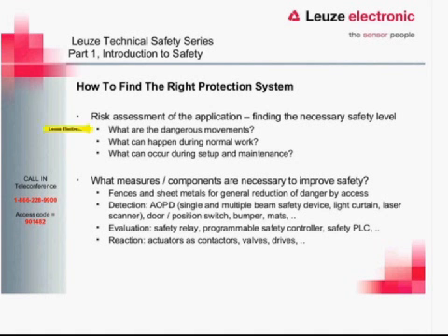So then we find, well, what are the dangerous movements? Is it a spindle? Is it a press coming down? Is it a pinch point on a gear? What can happen during the normal operation of the machine that could expose you to those hazards?